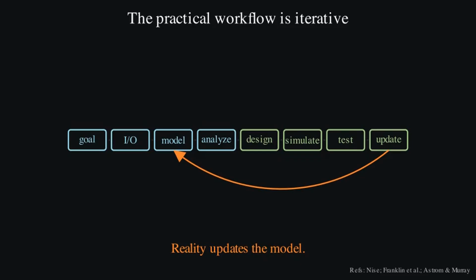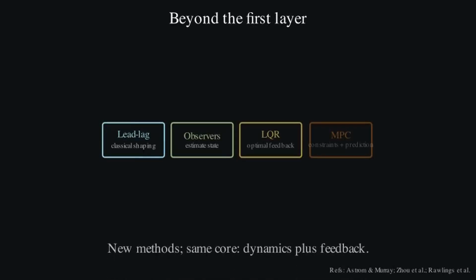The inverted pendulum makes eigenvalues physical. Hanging down is naturally stable. Balanced upward is naturally unstable. Feedback measures angle and angular velocity, then moves the base so the unstable mode is pushed back into stable behavior. In state space language, the controller changes the closed-loop eigenvalues.